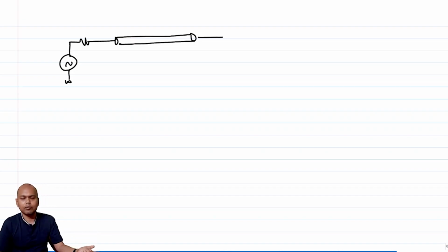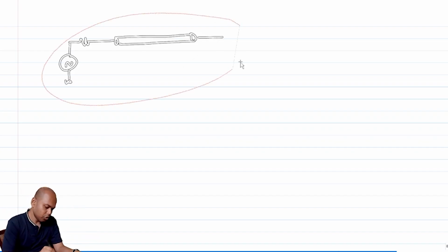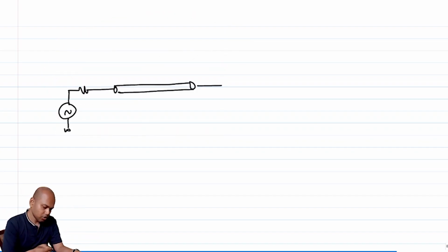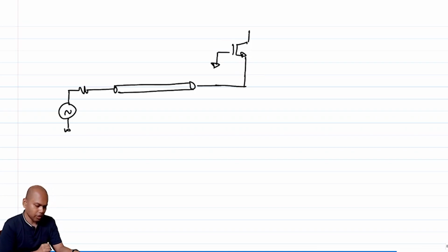What other things do I know about? I know about common gate amplifier, right? Let's see common gate amplifier. In common gate amplifier, the input goes to the source. This goes to the source. The gate is incrementally grounded. And you have probably some resistance Rd.